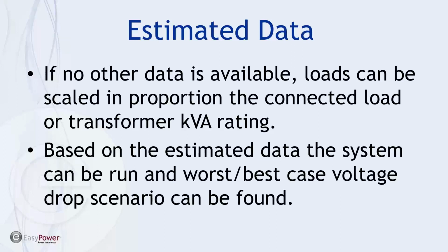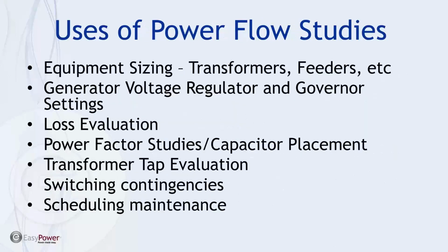But based on these estimated data, you can run a worst and best case scenario for your load PowerFlow calculations. PowerFlow studies can be used for equipment sizing, generator voltage and governor settings, loss evaluation, and trend analysis, and predicting issues with equipment.